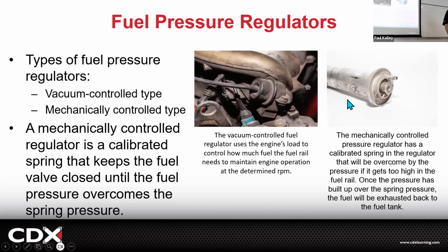And then fuel pressure regulators can be different types. Vacuum's common. If this one rips, you'll have fuel in that vacuum line. Probably that's the most important one to be worried about. Go ahead. Most cars have fuel pressure sensors.